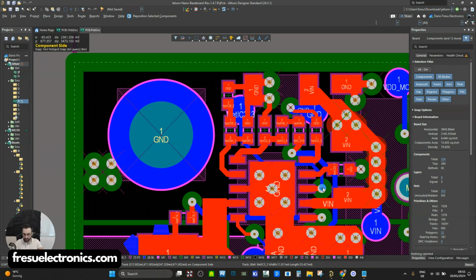One is to reduce the transient of the required current, but this means that we will have an impact on the timing and also on the efficiency of the PDN, of the system. The other one is to reduce the impedance of the PDN, particularly the inductance of the PDN. This is clear because as designers, we can have the most impact by reducing the inductance of the PDN. We cannot really change the requirement of the transient current.